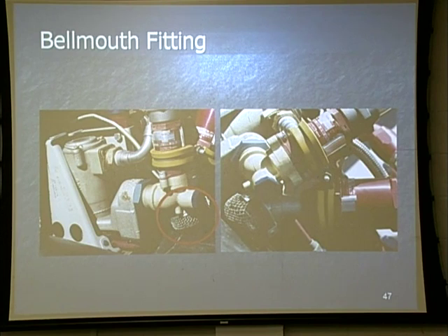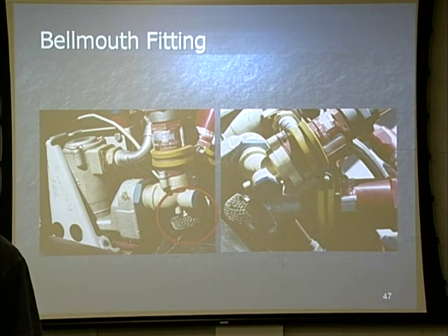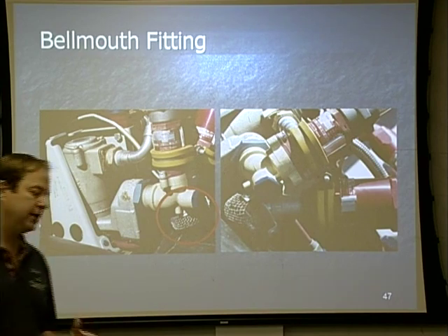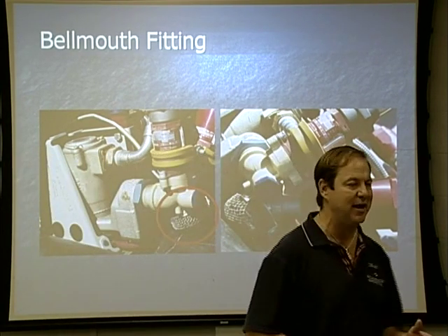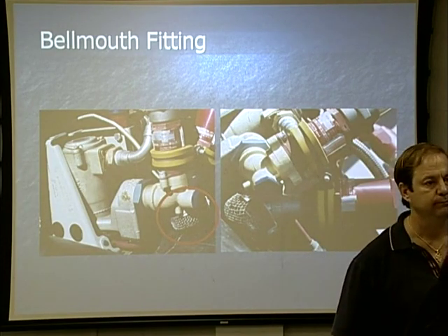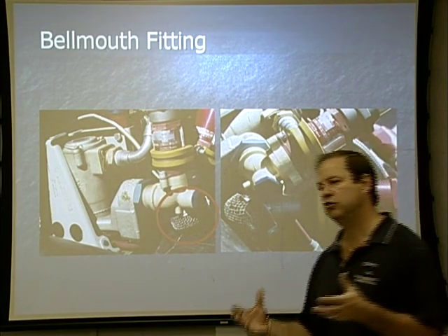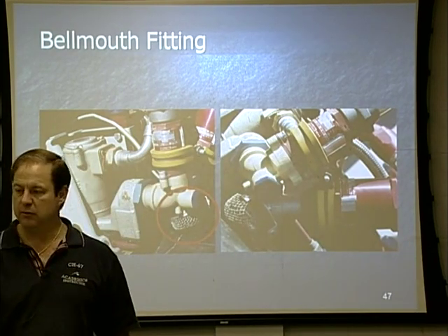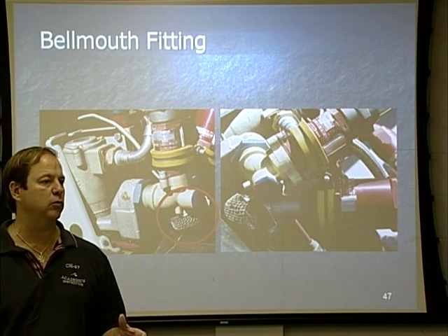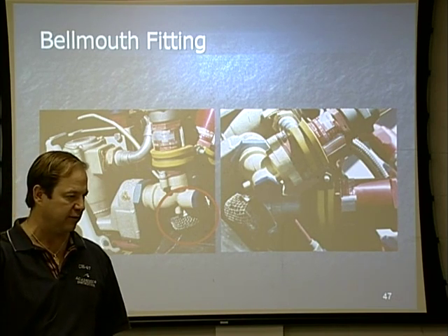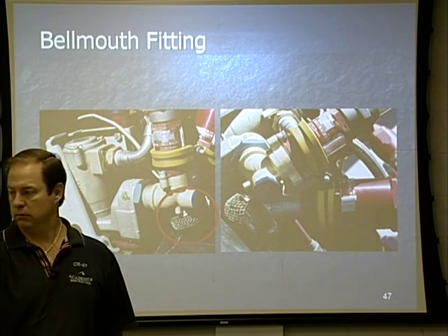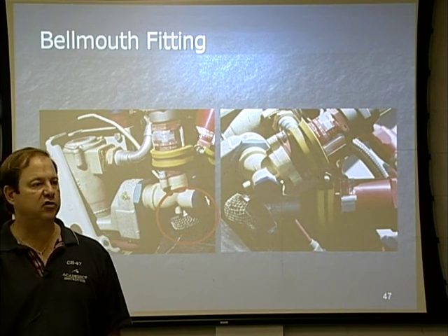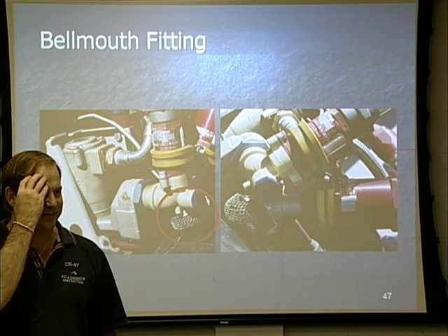Now, why is that important to understand? What caution do I have in my operator's manual? Nose low attitude. Avoid nose-low attitudes. Now, reality is, if you pay attention to your PPC data, this should not be a factor. Why? Because in the case of low fuel pressure, to get the max extended range, we know what airspeed we're going to go to, and that's going to give me a fuselage-level look.